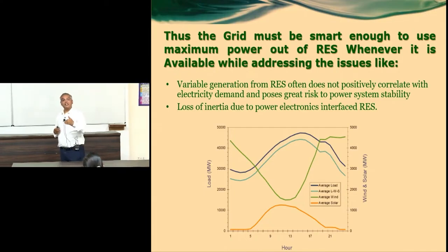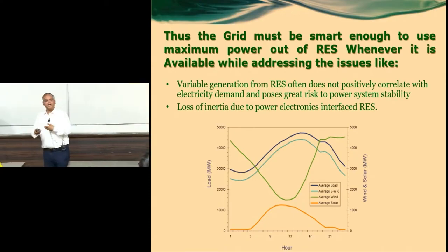So these are the standards coming into the picture, because now the batteries are going to give you virtual synchronous inertia or synthetic inertia. Well, inside the rotating mass, what is there? Kinetic energy. If the load suddenly increases, the speed of the generator will slightly decrease by that amount, because the energy is half J omega square.